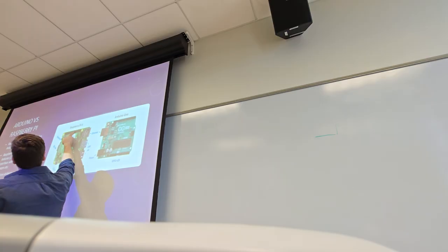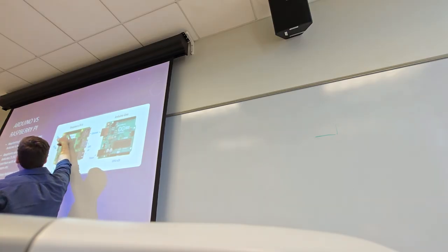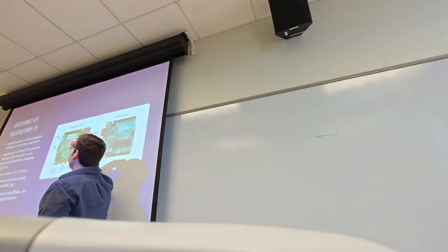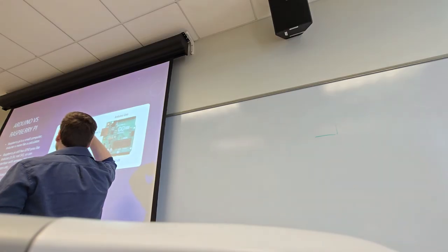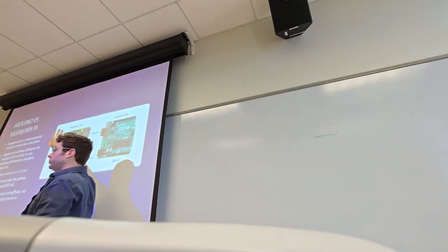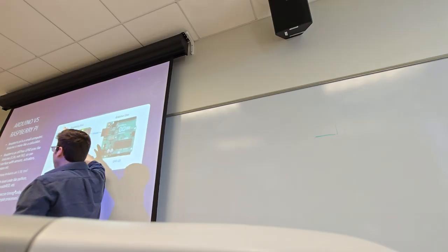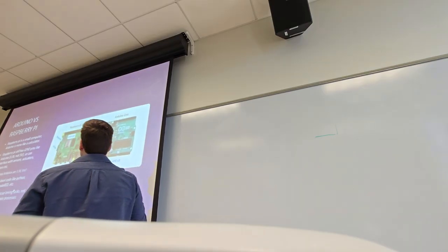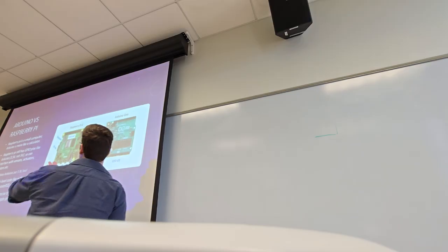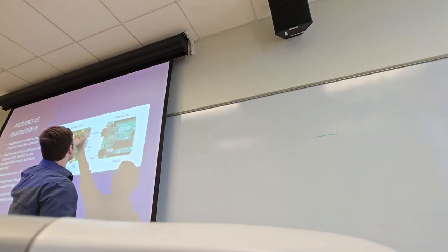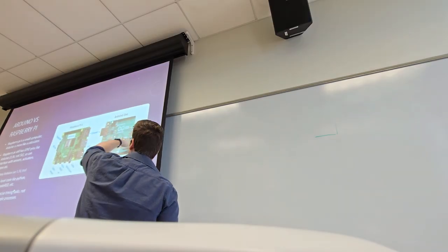It has general purpose input-output pins. Okay, it can talk to sensors, it can command motors. It's only 3.3 volts, so servos will have a hard time talking to it. Most servos are 5 volts, but there are solutions for that. But a lot of sensors will plug right in. You could plug an I2C sensor into a Raspberry Pi or an Uno.